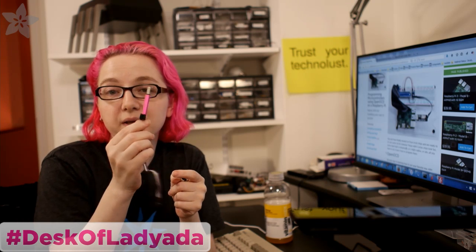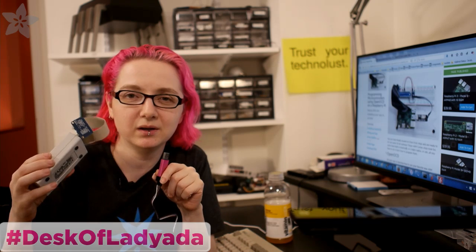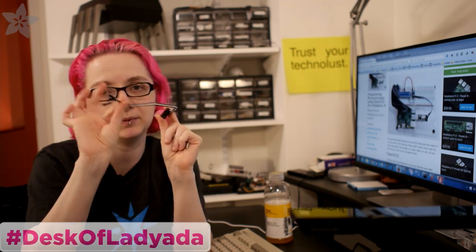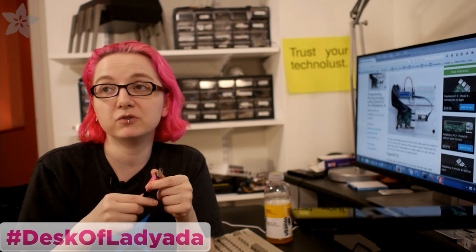You can also, if your chip is supported and it is okay to use it with, use the ST-Link, and the ST-Link is way simpler. It also does SWD, but it just doesn't have every weird exception. Really every chip company is a little bit different. We use OpenOCD with the ST-Link, and it's a little dongle, basically USB in and then SWD out on these wires. You can use this for the ATSAMD21 and the nRF51822. It works fine. These are a couple bucks, they work great, and they're actually a little bit faster than J-Links sometimes.